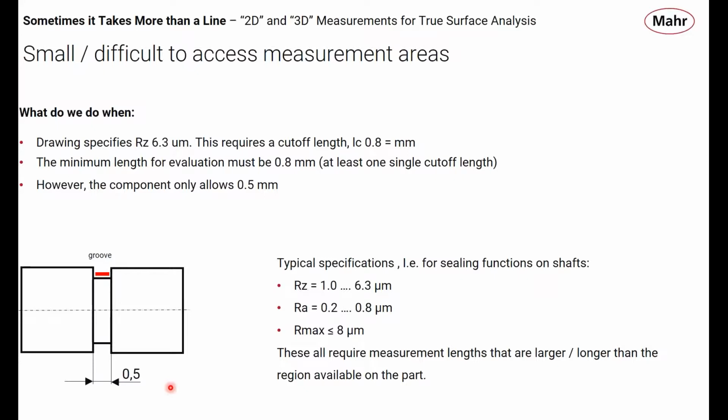That's all fine. In this case, there's a reason that ISO provides that guideline. If you only have a couple of 100 microns of strike length, and you have a fairly large roughness in that area, you need more than a half a millimeter or a quarter of a millimeter of data, just to be sure that your data really represents what's going on in that groove.